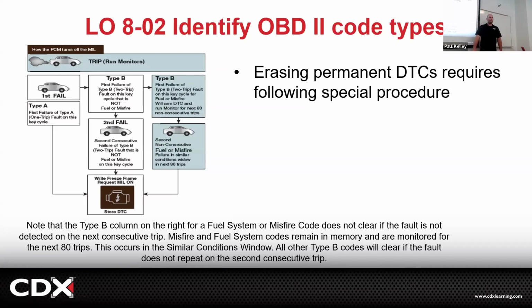So let's say it was a misfire. The car comes in, it has a misfire code. You throw spark plugs at it. You try to clear it. It won't clear because it's permanent. You drive it around. It won't clear because it's still failing the monitor. You didn't fix it. You're stuck with it now.